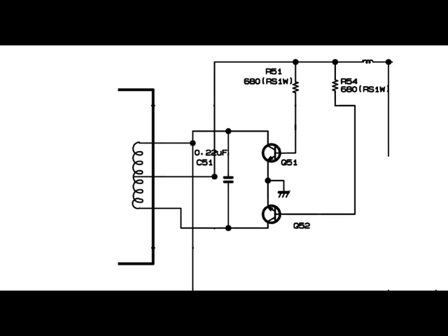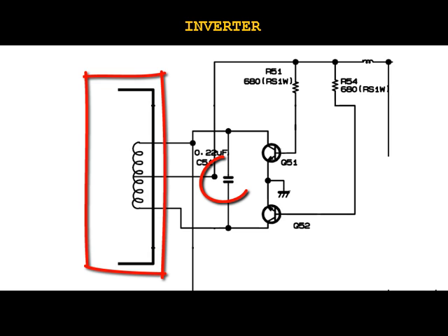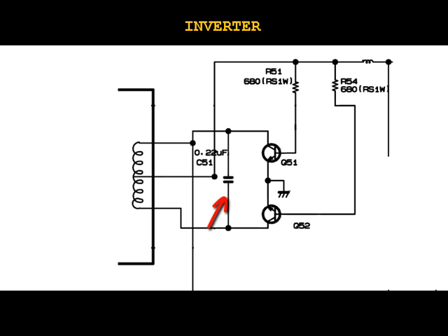Let's begin with a simple circuit that is used in LG Zenith brand for small TV screens. The oscillator circuit consists of the following elements: the transformers, the capacitors, the transistors. This is the primary side of the transformer, and in parallel there is a capacitor. These two elements easily oscillate or shake for a certain time when a current passes through them or is suddenly discontinued.